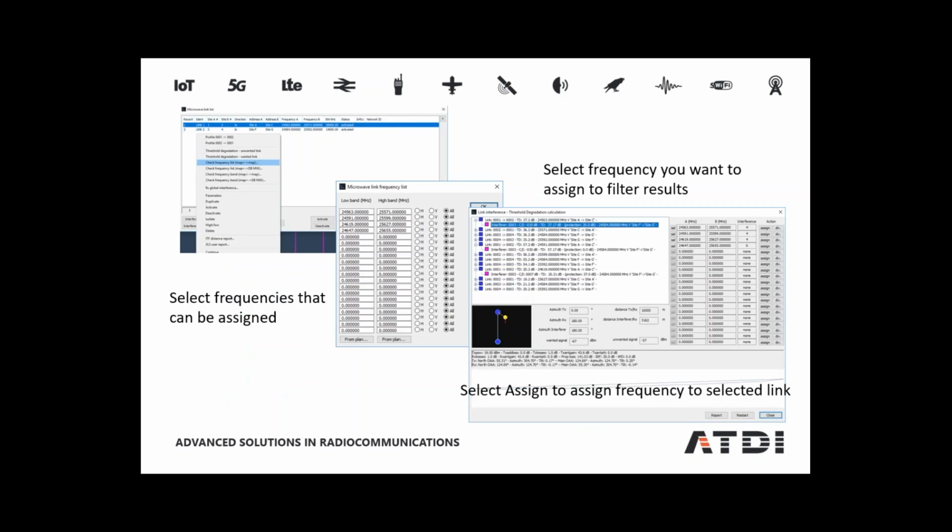Yeah. Hi, just a very quick question on that before we move on. If we use directional antennas, how would that change the interference in the example that you've used? I think probably the interference would go away, which is why I used omni antennas in the first place. Let me do a frequency assignment, then I'll come back and we'll change it back to 25 gigahertz on each link, and we'll put antennas in, because that actually solves the problem as well. So we'll do a frequency assignment to solve the problem, then we'll change the antennas to solve the problem. So a frequency assignment.